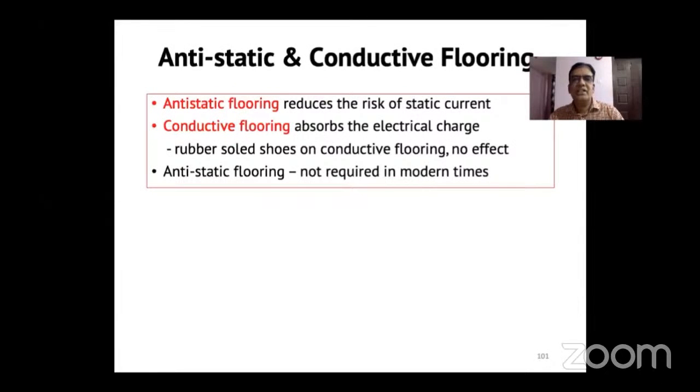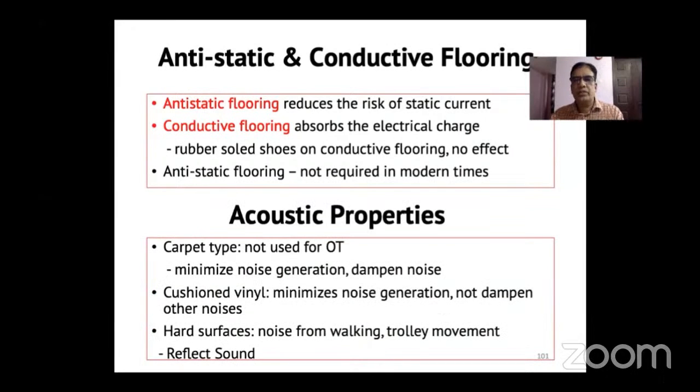And even anti-static and conductive flooring, we had been discussing it very actively about two decades ago. Anti-static flooring reduces the risk of static current. Conductive flooring is the one which absorbs the electrical charge. So please note the difference. And in conductive flooring, if you are using rubber-soled shoes, there won't be any effect. Only if you are walking barefoot, it's going to make a difference. And in general, because we are not using flammable anesthetic agents and techniques, anti-static flooring is no longer required in modern operation theatre. And even acoustic properties of flooring are also mentioned.